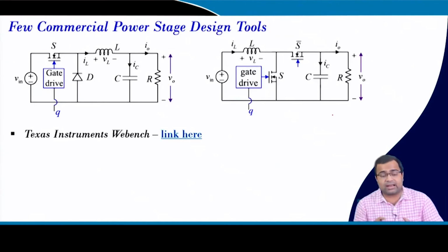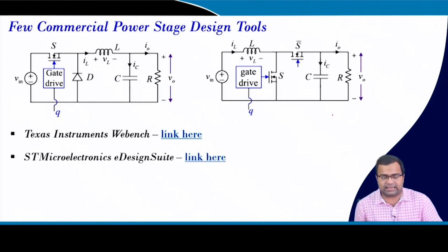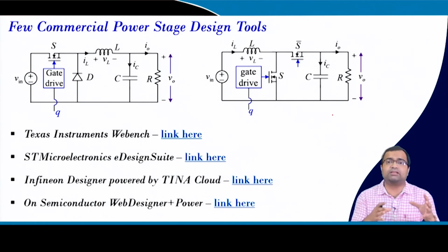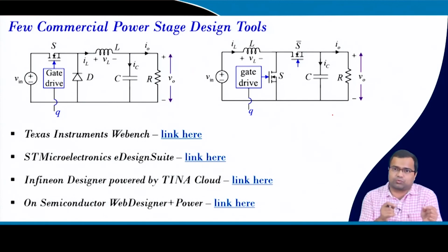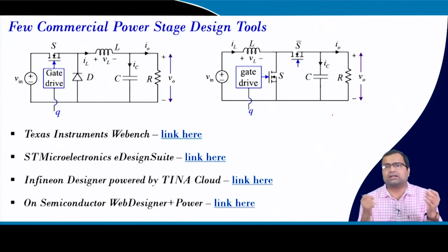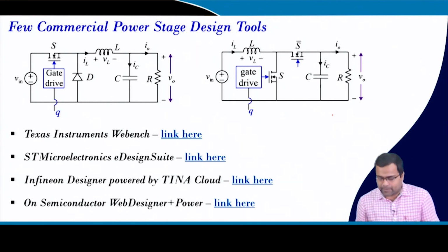Now, there are a few commercial tools, and I am presenting a few of them, like Texas Instruments WEBENCH, then STMicroelectronics eDesign Suite, Infineon has its own, then ON Semiconductor, and other industries also have their own tools. If you go to such a tool and give your input, output voltage and load current specification, it will create a bill of material, so that you can even know the parts of the inductor and capacitor. It will be helpful in the power stage design also. Okay, but you can have your own controller.